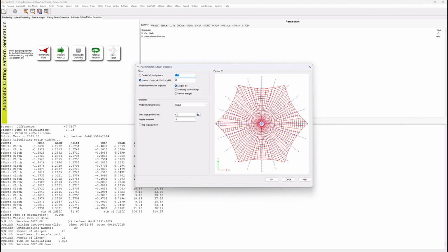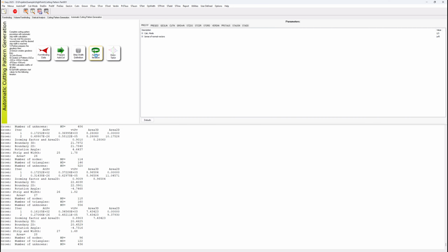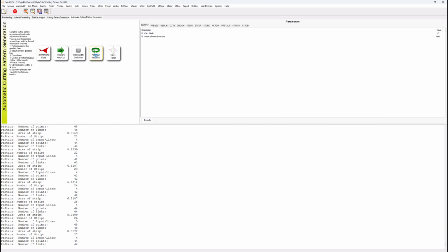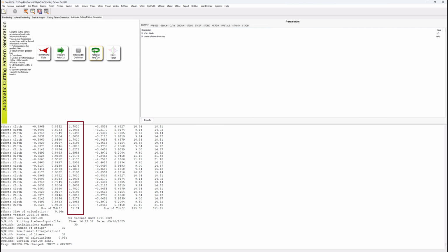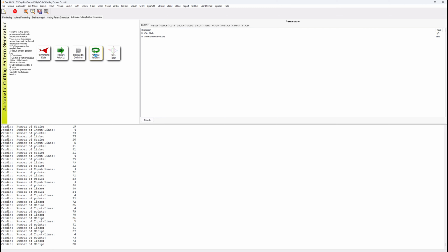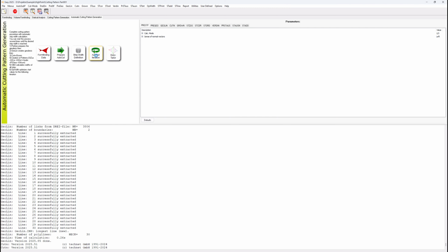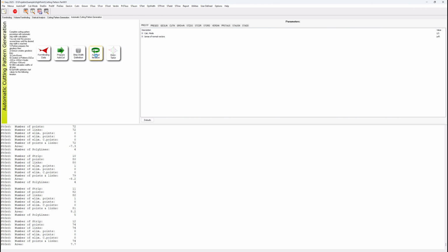By clicking this one, the parameter window opens again. Here we change the value from 20 to 30 strips and confirm the input with OK. We can then start the final iteration calculations, as usual, via clicking the tile with the green round arrow. After starting the calculation, the first iteration step is executed. Information about the calculation progress is displayed in the lower information area. It becomes clear that the strip widths are not yet fully adjusted. Therefore, additional steps are triggered by clicking again.